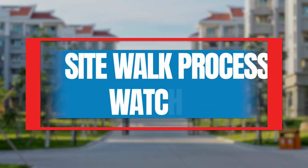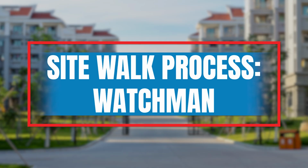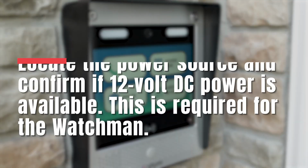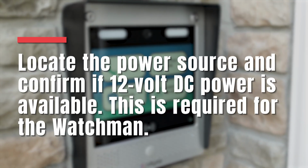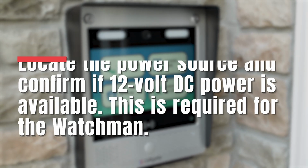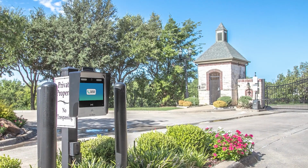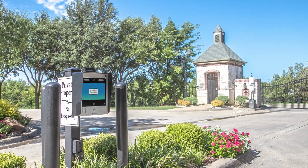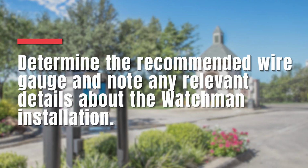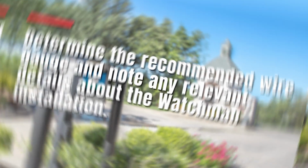Site walk process, Watchman. If a Watchman unit is part of the installation, with the installer, locate the power source and confirm that 12-volt DC power is available. This is required for the Watchman. Measure the distance from the power source to the Watchman location. Determine the recommended wire gauge. Note any relevant details about the Watchman installation.